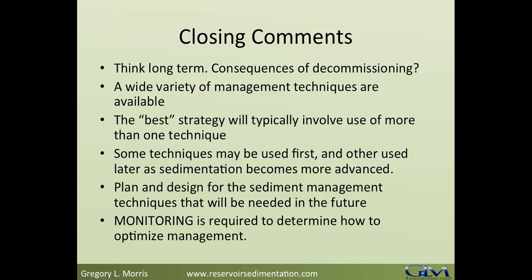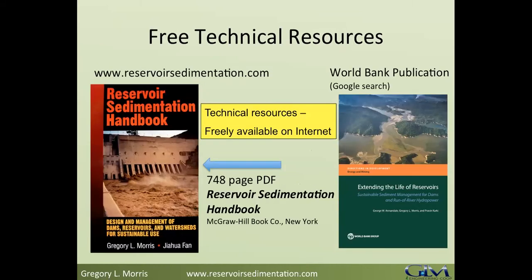Plan and design for the sediment management techniques that will be needed in the future. So, for instance, if you are going to employ one technique now, but you know that you're going to be needing to use a second technique, say 50 years in the future, think about that future requirement and plan your infrastructure modifications so that they help support future management rather than work against it. And finally, monitoring is required to determine how to optimize management.